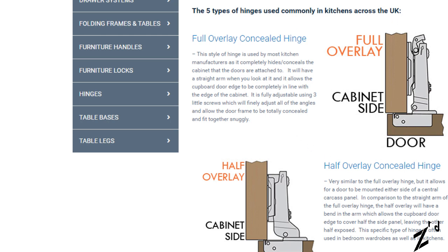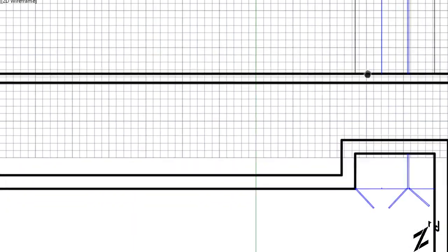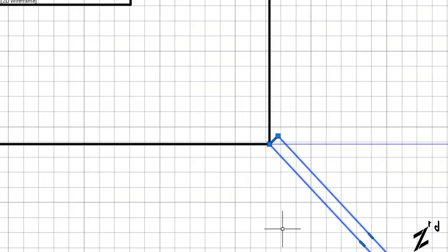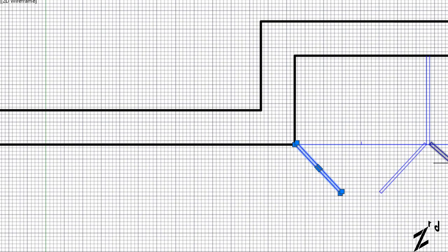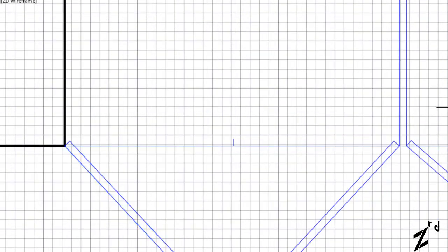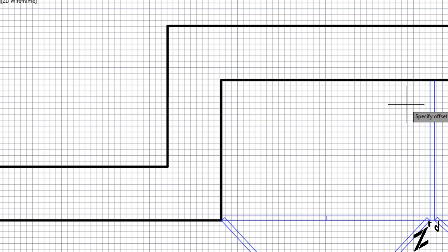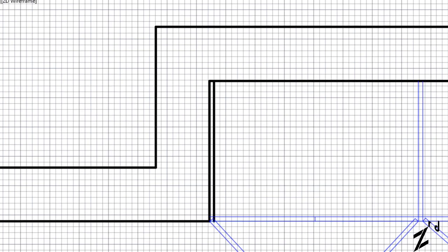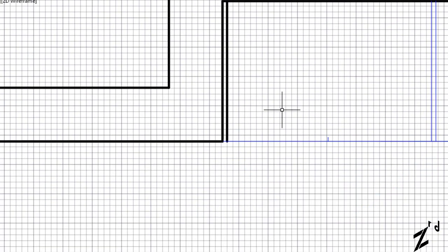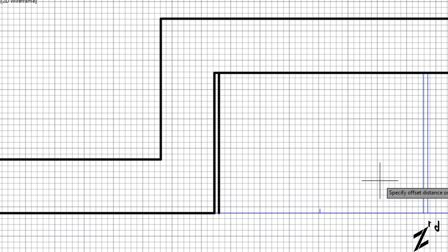All right, I'm just going to draw this into the drawing here. Obviously, I'm not going to draw the actual hinge itself. I don't have that much time, honestly. First of all, let's move this particular frame by 2 centimeters back. Let's add a couple of extra frames to the sides for our support. Let's trim it decently to the outside trim. Delete that. Delete our three doors. Offset 1.9.